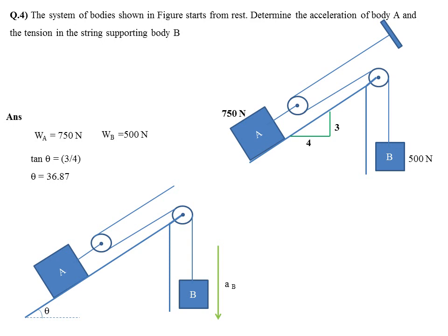Or you can take block A moving downward direction. If block A is moving downward direction, block B has to move upward direction. For this case I am assuming the direction of block B as downward direction. So downward direction block B is moving, so that direction is the acceleration, that is AB, acceleration of block B.